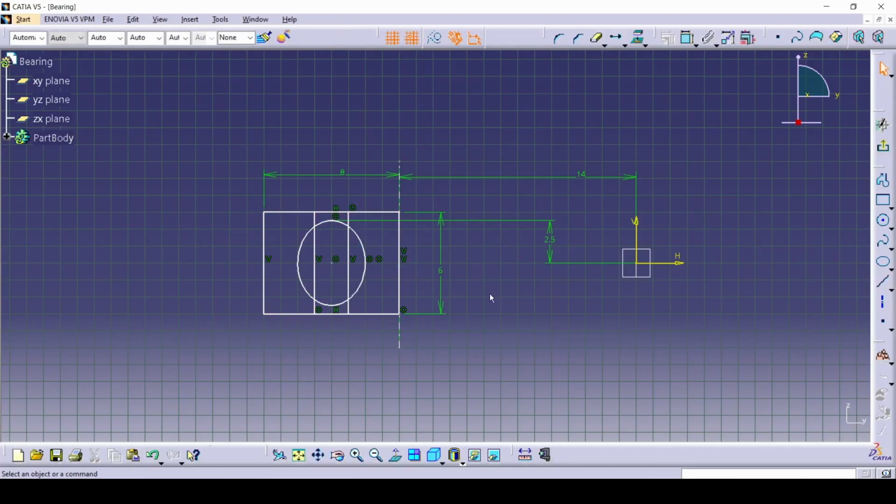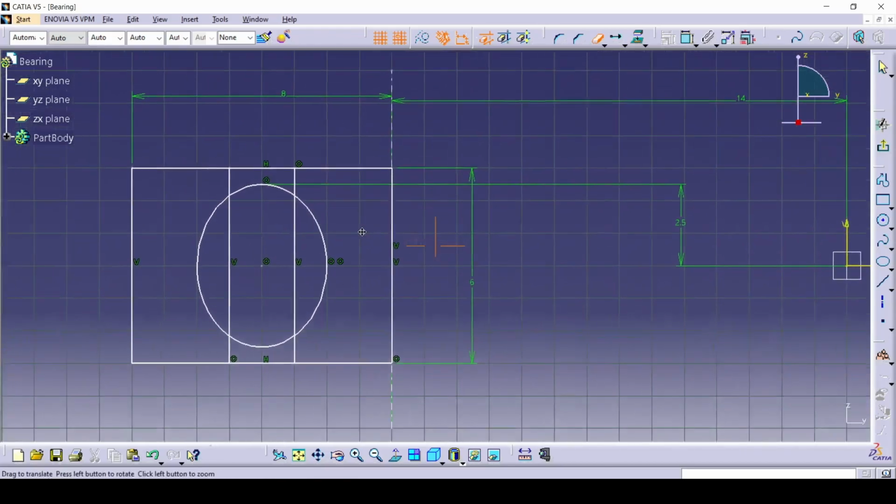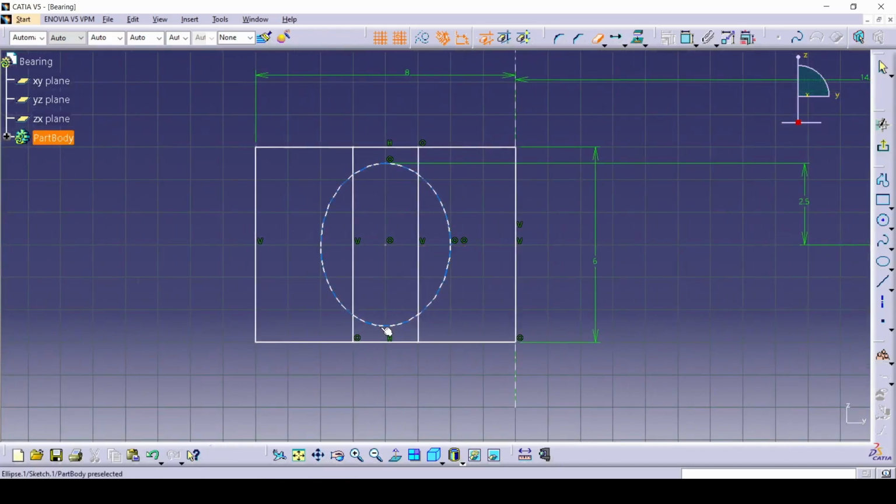Now next up we have to use our quick trim command to remove some spots, because we don't need this for our next operation. So double click it, very important to double click it, zoom in here a little bit, and just delete this line. This line, just follow me, and what I delete you should delete as well.